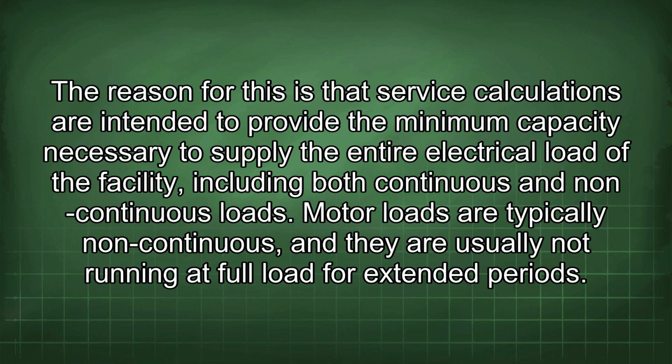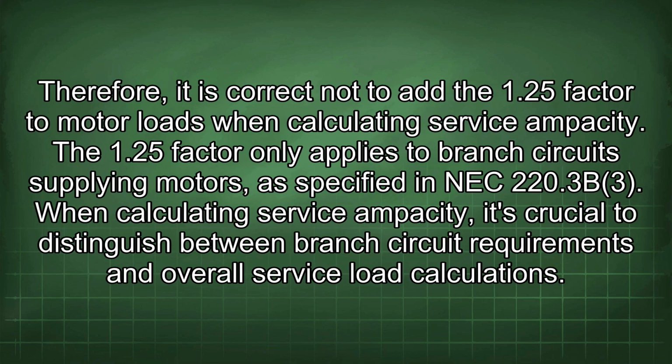Motor loads are typically non-continuous, and they are usually not running at full load for extended periods. Therefore, it is correct not to add the 1.25 factor to motor loads when calculating service ampacity. The 1.25 factor only applies to branch circuits supplying motors, as specified in NEC 220.3B3. When calculating service ampacity, it's crucial to distinguish between branch circuit requirements and overall service load calculations.